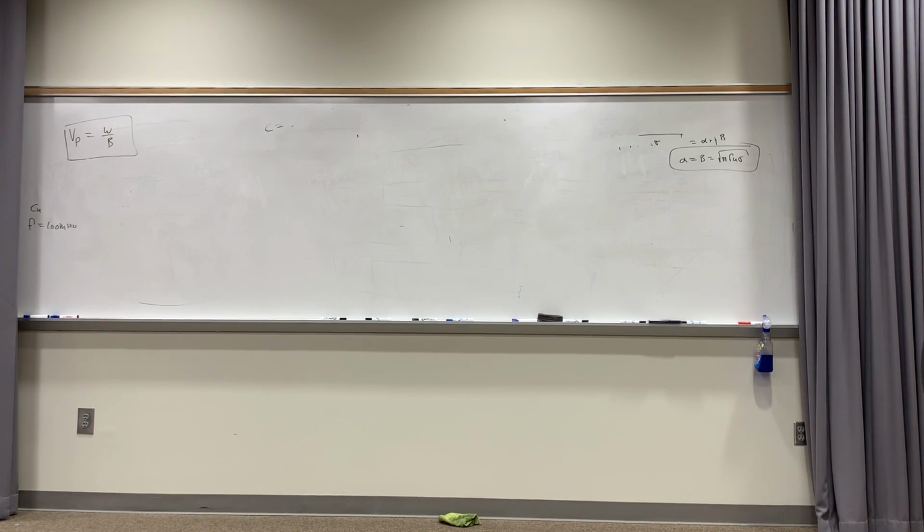Omega t minus beta z, and we saw if we froze time and just had beta z, so make t go to 0. We know cosine of minus beta z is the same thing as cosine of beta z, right? Because it's an even function. And when z is 0, that would be the start of the wave phenomena. And when beta z was 2 pi, it would be one wavelength down, wouldn't it? So we had beta times the wavelength equal to 2 pi.